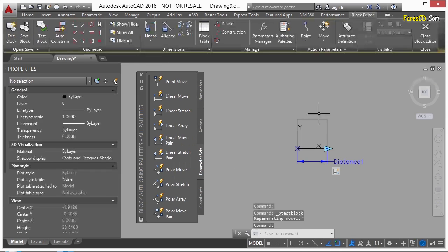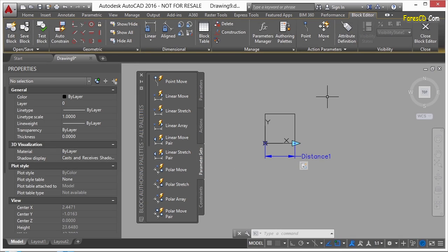So let's close this and we're back inside our block editor. So you can see here the test block tool, the command, the option, or that mode really helped me out to troubleshoot what was going on while I was creating this dynamic block. So it's very important to use that. Don't assume that you've done everything correctly. You can miss a step so easily, and it's very important to get every step correct. So I tried it 3 times, and on the 3rd time, well, that was the charm, and I finally got it correct. So when you're making, especially making complex dynamic blocks, keep testing. Make sure each part is working the way it should be working before you move on or progress to the next step, or else it just won't work correctly.